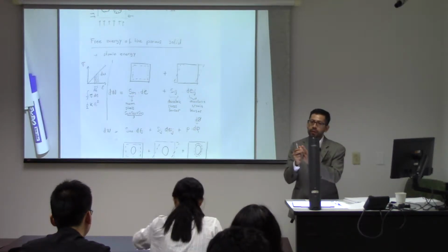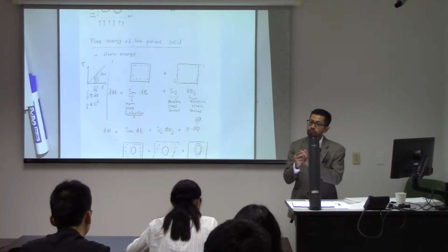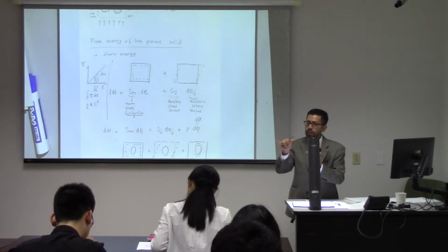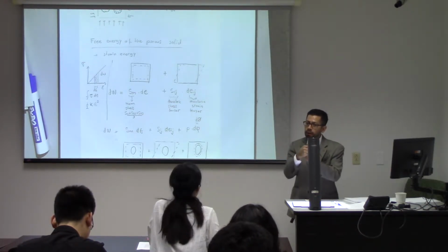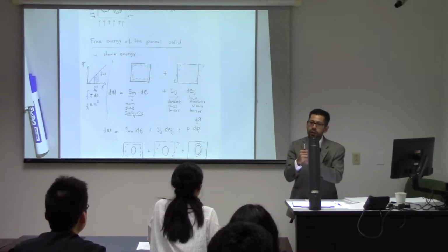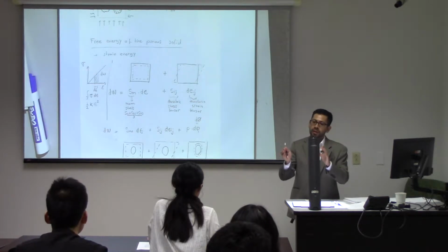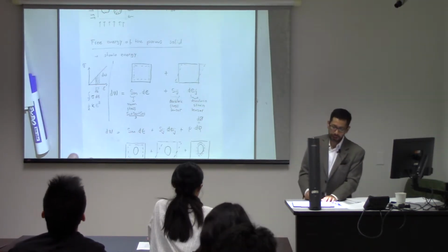We can have constant pore pressure, or the opposite of constant pore pressure. Pore pressure will be closer to prescribed stress, constant pore pressure. The opposite of displacement constraint is going to be constant mass, constant fluid, and that's something that we're going to call later undrained loading, because the amount of fluid inside the porous solid is not going to change. Okay, we'll get there later on.